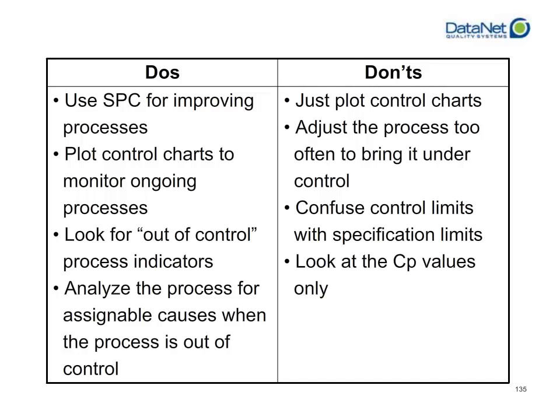Do not confuse control limits with specification limits. They are not the same thing. Control limits is the voice of your process. It is calculated from the data itself. Specification limits come from your customers, be it internal or external. If you go out of control, that means your process is not statistically in control. Your process is likely changing or there's an assignable cause acting on it. If you're out of spec, that means that you've actually produced bad product.